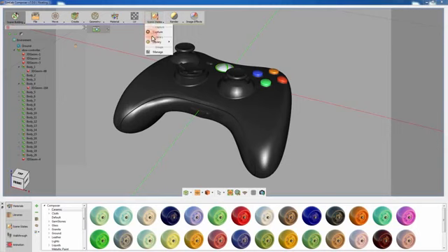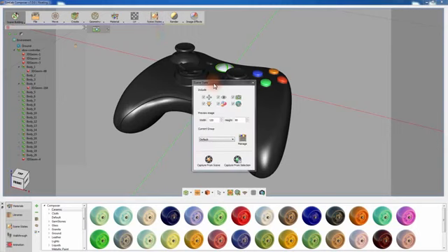Click on the Scene States menu and select Capture. Scene States is an option that allows you to save several attribute preferences for your scene. Those preserved sets of attributes can be used in a 3D PDF document to turn the model into an interactive object with customizable properties. Some of the attributes that Scene States can capture are materials, cameras and lights, to name